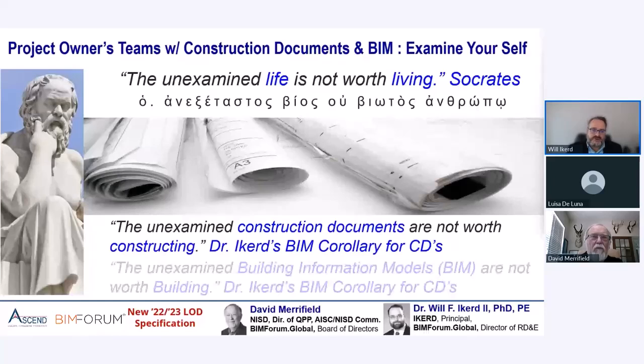And the mechanical penetrations for roof drains, for example, coming in, with the cow tongues attached to the facade, that's the purview of the mechanical engineer and then the plumber, in this case, MEP, but specifically the plumbing. Mechanical louvers. If this is tilt wall that's being used on a public school, for example, that must have tornado resistant design, there's a lot of coordination that goes into those mechanical louvers that have baffles that can handle closing off in a tornado event.